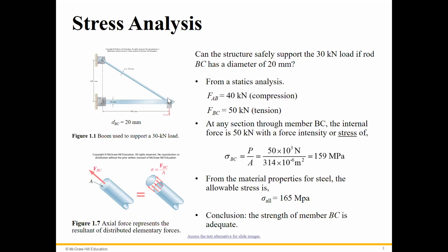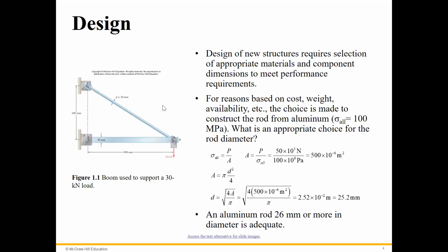For example, we have this structure, a current structure, and we know the section. Then we want to check whether it is good or not if we apply the force here. We find the stress, and then we compare with the allowable stress, and say, okay, this section with this diameter is good.